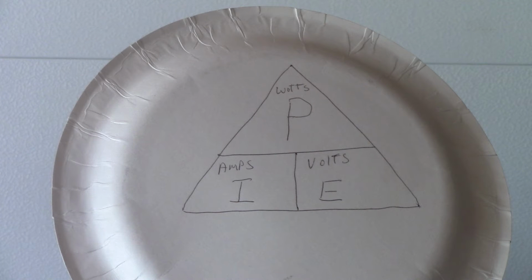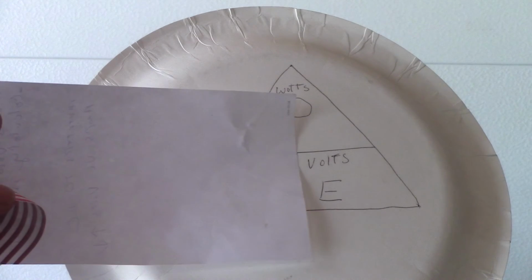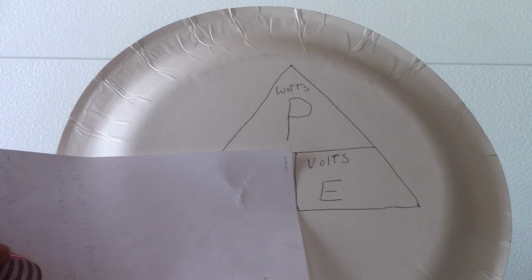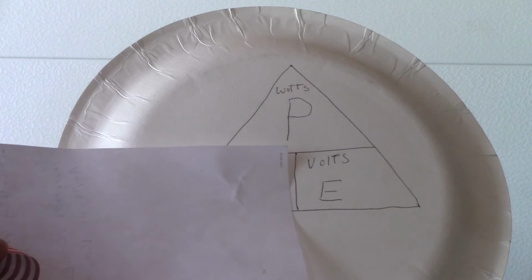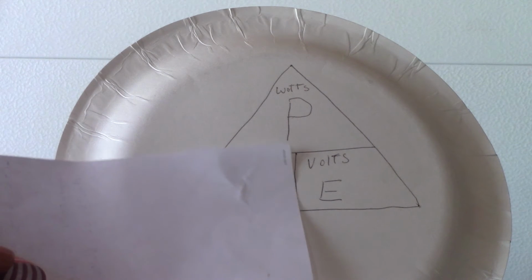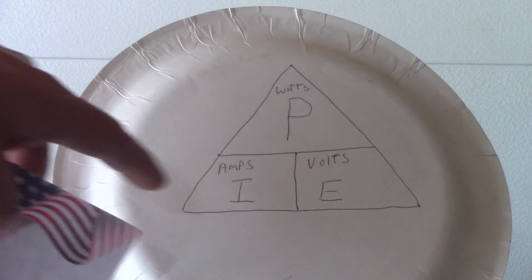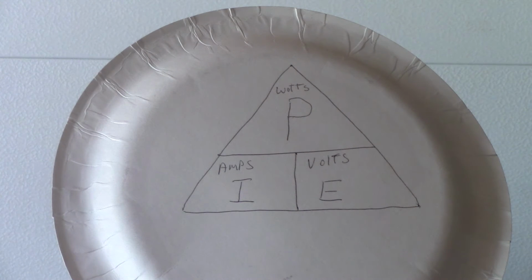And it's pure sine wave at 120. That's its output. Now on the other side of the inverter, say I'm running AC stuff, but it's still a total of 60 watts. How does that affect us? Well, if I'm now at 120 volts and I have 60 watts, 120 goes into 60 what? 0.5 times, or a half an amp. So we have half an amp now on the AC side.